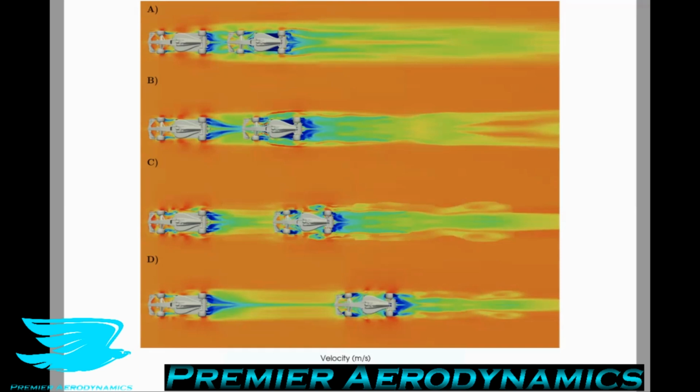It is seen that as the second car reduces the distance to the first car, its wake originates at a separation region that enlarges and becomes evident. Sorry, what they've discussed here doesn't really make as much sense, so I'll try to break this down in everyday English. What they're saying here is as the downstream car approaches the upstream car's wake, which is now pretty much a separation zone, is now engulfing the downstream car. So you now have this separation zone, which means that the flow isn't even aligned properly with the free stream flow hitting the second car.